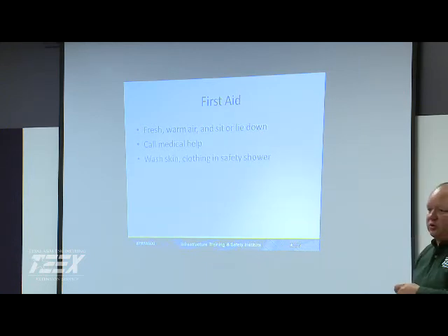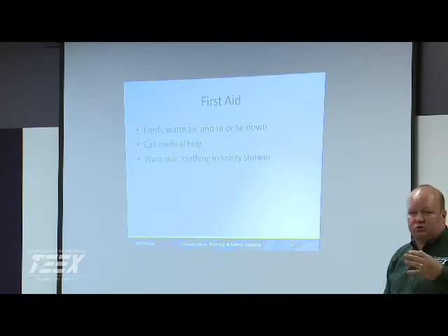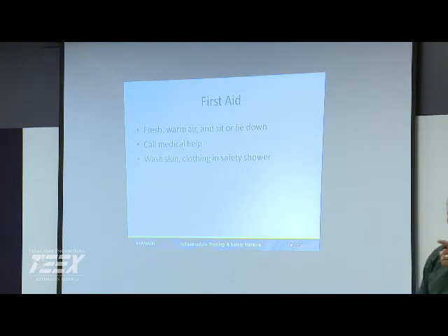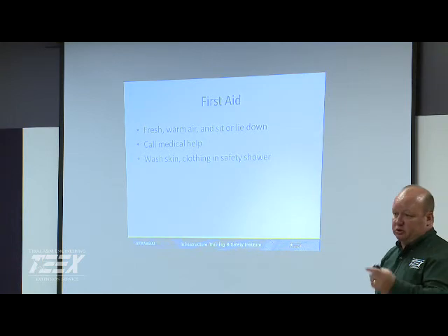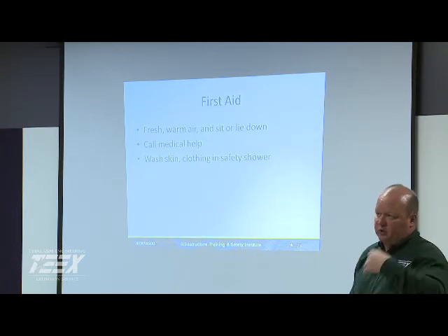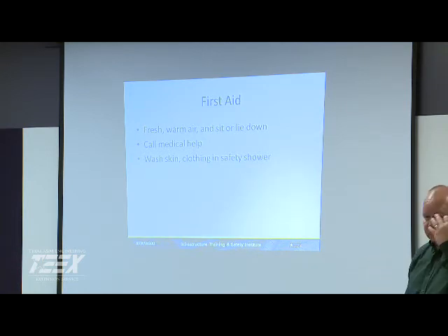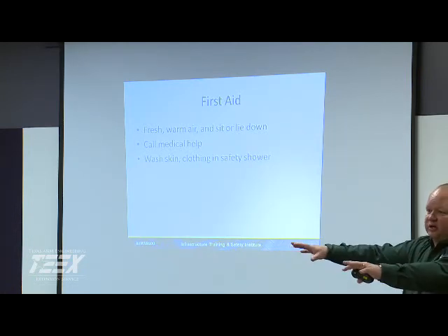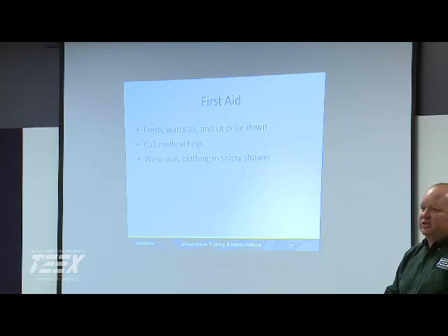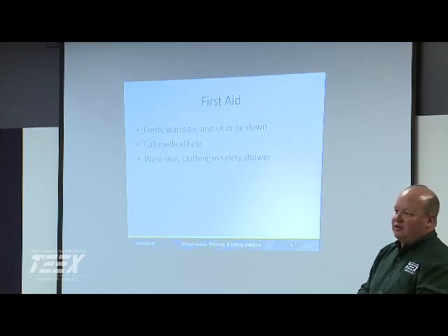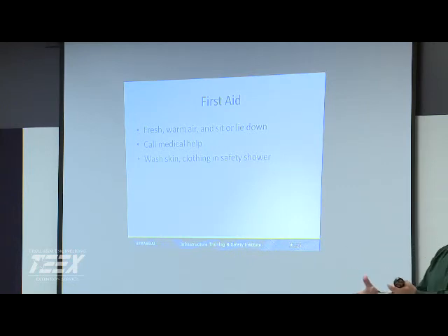You do need to make sure you have showers, and even like with using bleach and metering pumps. I don't know if y'all have a shower nearby, but that's something that's important to think about. Because if you get sprayed under pressure, especially in the face, what are you gonna do? Where are you gonna go? Stumbling around trying to figure out where you're at is not the time to think about, oh, I need an eye wash station or something. It's real easy to set them up on a sink or whatever else.